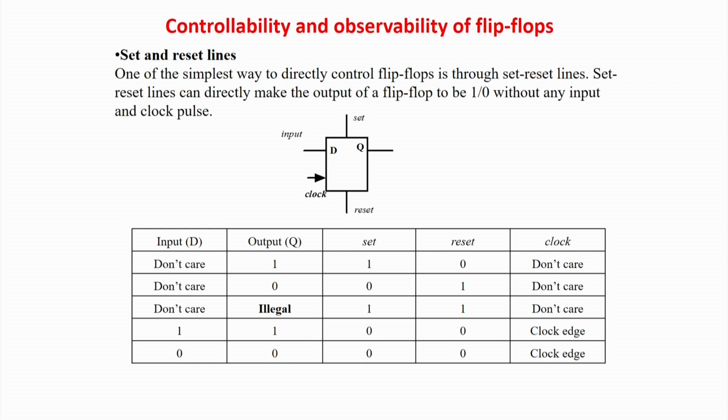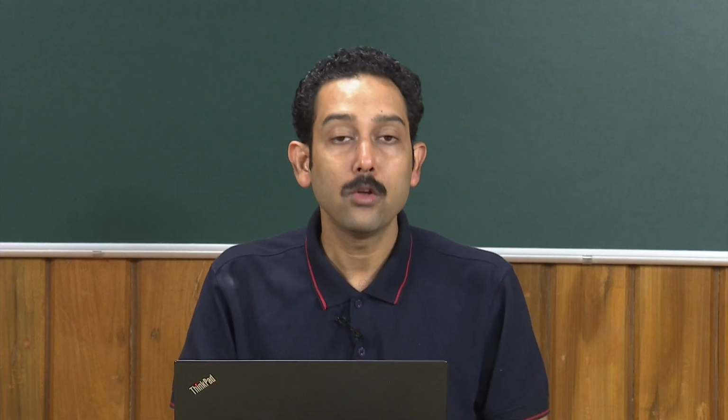So we require that our complexity should not grow more than the complexity of testing a combinational circuit. In combinational circuit testing, what we have seen is that even if there are 2n stuck-at faults, the number of test patterns will be much less, because one test pattern will cover multiple faults. And not only that, for one fault, a maximum of one test pattern is required. That is the worst case. But in this case, as you can see, things have started blowing up. So how to do it?